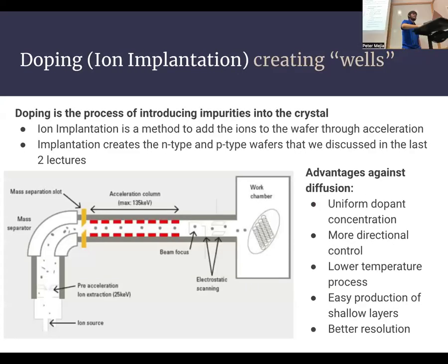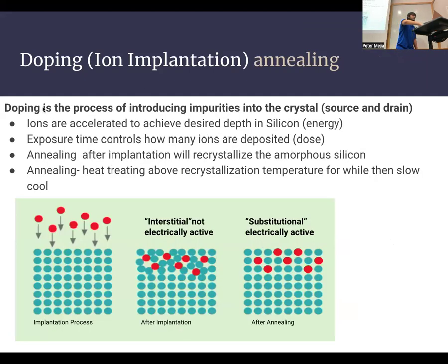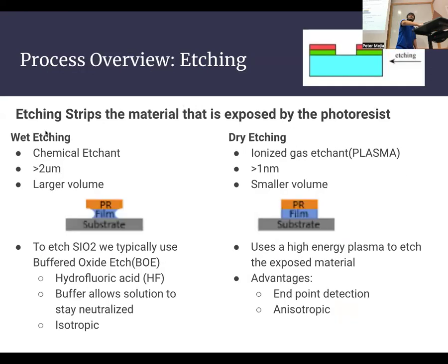All right. So now we can talk about doping. What keeps it from eating away too much of the film layer? So you're talking about the wet etching. Yeah, it's the chemistry. If it's HF and silicon, it just won't eat it. That's kind of why they chose this particular HF as opposed to maybe some other acid like sulfuric acid that'll just demolish everything.